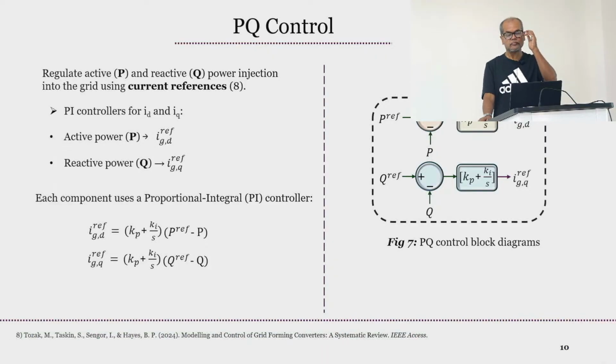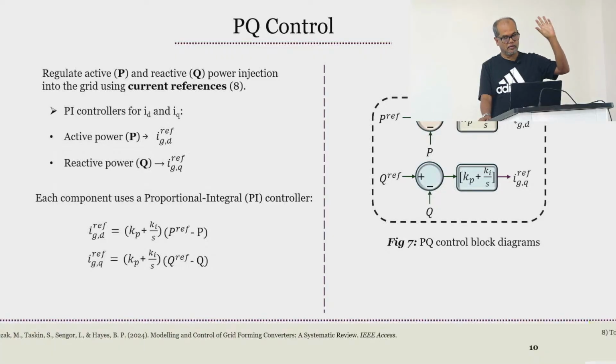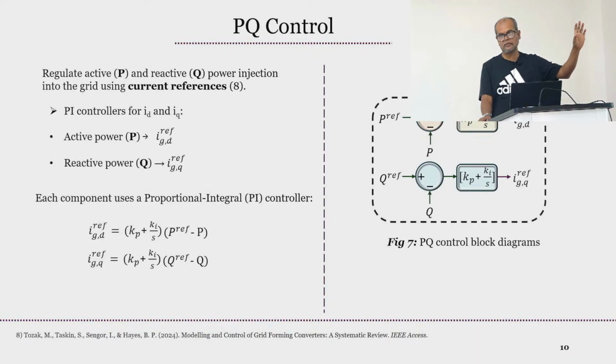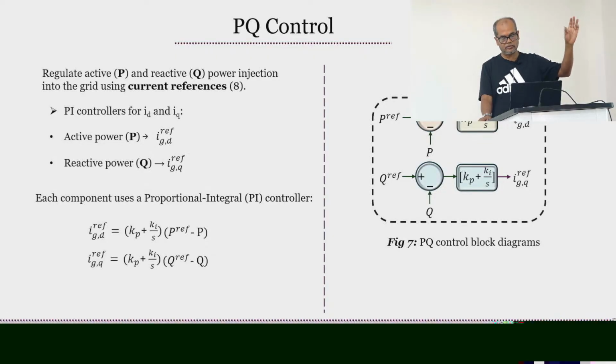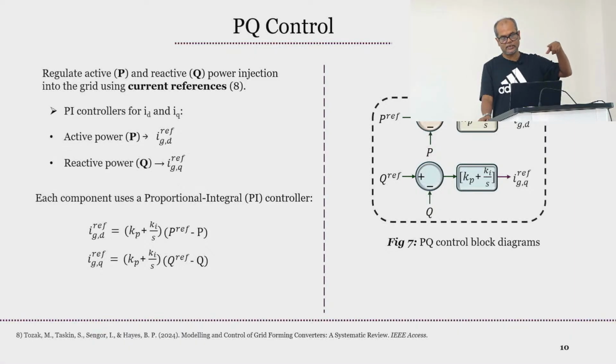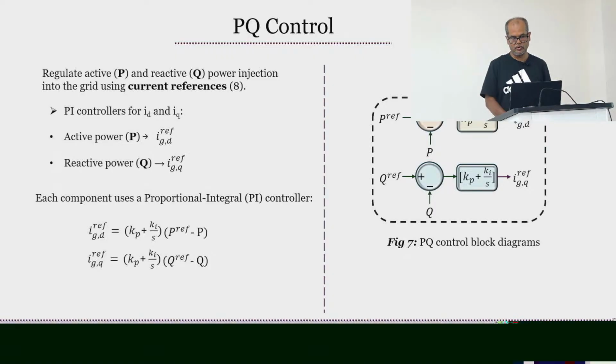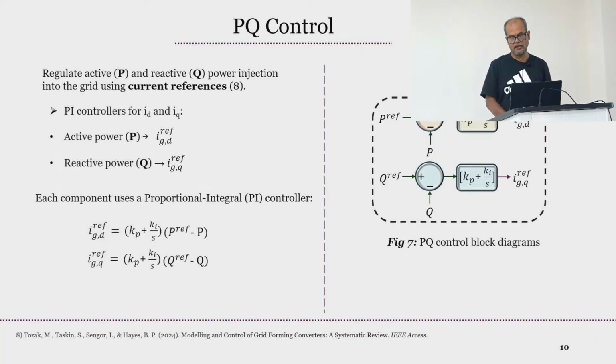Once you have the state space model with four matrices, you can easily get the transfer function, and then use root locus and many other ways, such as Ziegler-Nichols. There are many techniques available to determine these constants.